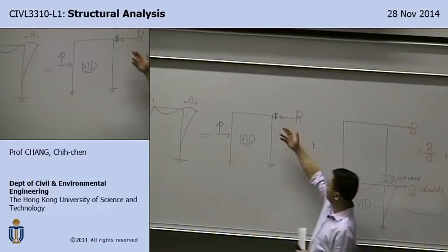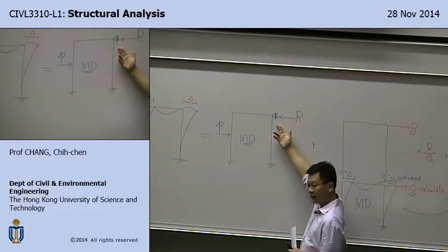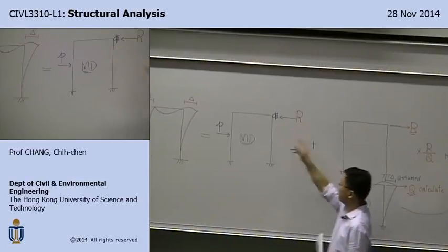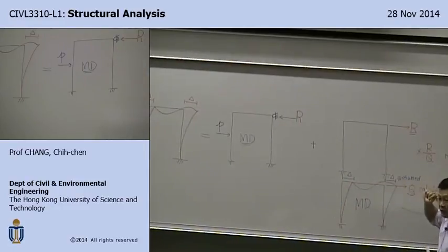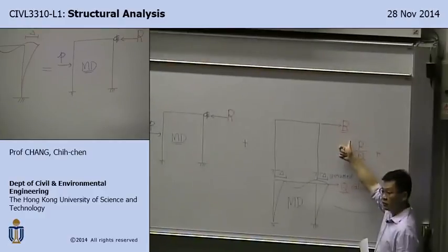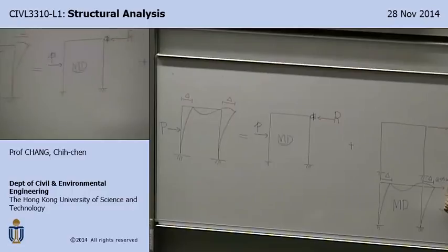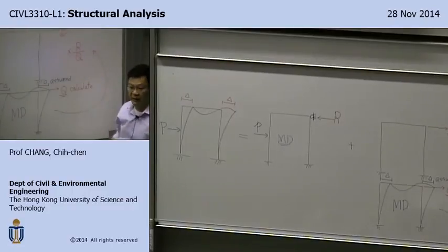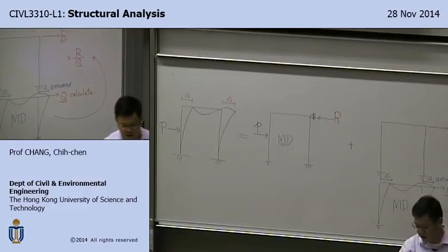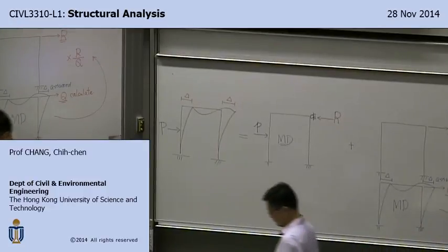Right? First, you assume it's roller support, no translations, and then calculate the reaction force, back apply the reaction force, but through the assumed displacements, back calculate how much the force is required, and then scale it back. So that's ways to address the issues of translations.